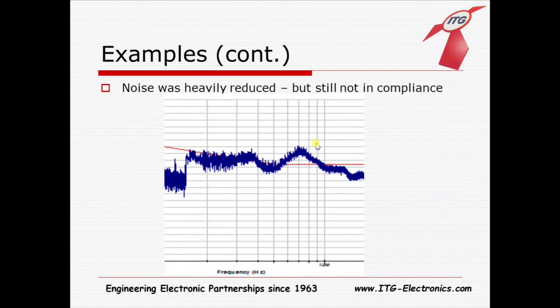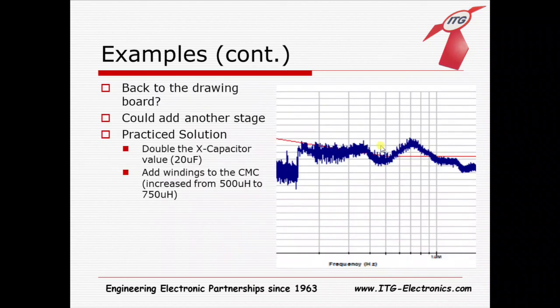And so in looking at this, we decided to increase some of the values of the components since we had some on hand, knowing that this could be a possibility. Well, yeah, sorry, I already gave it away a little bit. But some of the other options would be adding another stage of filtering, which would bring this down significantly, but would increase the physical space of the filter. So some of those parameters of design we talked about earlier.